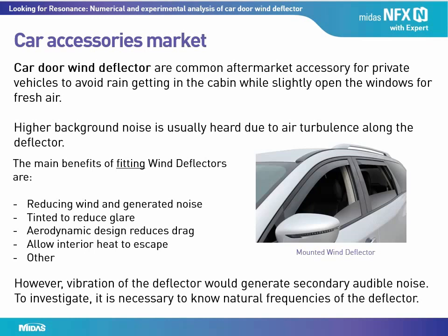You may notice higher wind noise after the deflectors are installed. The deflectors change the aerodynamics of your car and create air turbulence along themselves. Vibration of the deflector would also generate secondary audio noise. To investigate vibration-induced noise, it is necessary to know the natural frequencies of the deflector, which frequencies fall within the human sensitive hearing band.